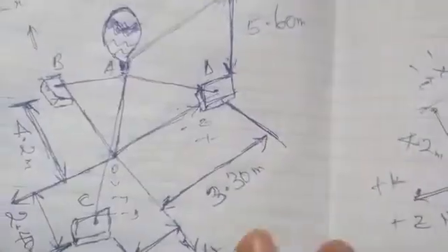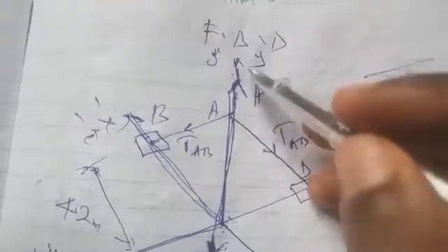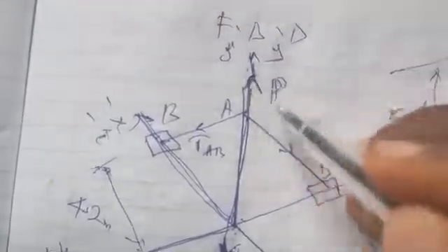Okay, so if we do that, we'll obtain: summation of T equal to tension in cable AB plus tension in cable AC plus tension in cable AD. Similarly, it is also important for you to know that it was given earlier that there is a vertical force P acting at point A, which we included in our free body diagram. There is a force P, and we assume that this force is pointing upwards, so it's positive. It's also not wrong if you assume that this force is pointing downward.